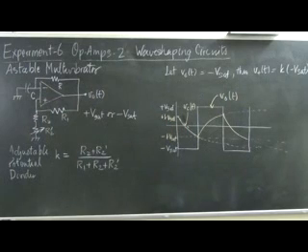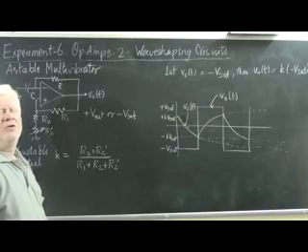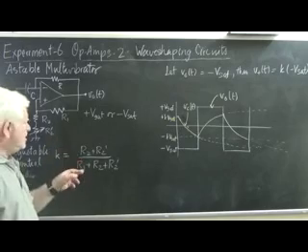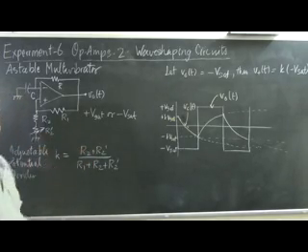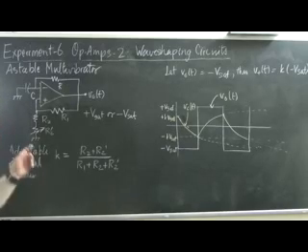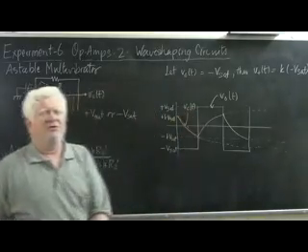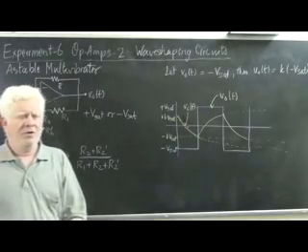There are two ways of manipulating the frequency of this circuit. One is to adjust the value of k, which is done of course by using the potentiometer that we have allowed ourselves here. This potentiometer will change the value of k, and it will therefore change the switching levels of the op amp.